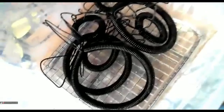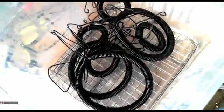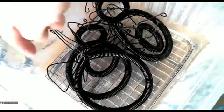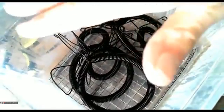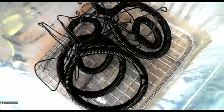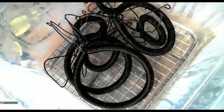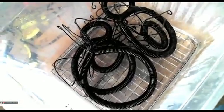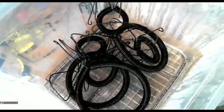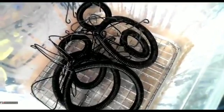It should be like this when you finish off doing the second or third coating. Otherwise, you're doing something wrong, and you have to go back to the basics and see what's in here. I've got the caustic, but I also have a chicken mesh on the bottom that lifts the coil off so the caustic is not touching it. It's just above the liquid, so it's not hanging inside the caustic. It's close, but not too close. Make sure you have enough water and enough caustic, but that the container is small enough. If you have a large container, keep in mind that the temperature will drop really quickly, so it will not have enough interaction with your coils.